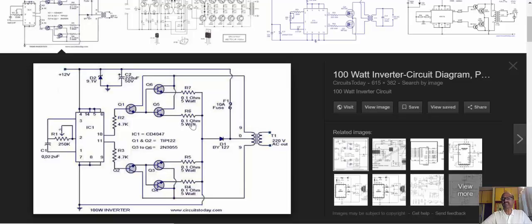So overall the circuit is not good, though it uses a digital IC. This is the variable resistance, and this is the capacitor to set the frequency, and once the frequency is set, this is going to be operating at that frequency. This is Q and Q bar. But a serious drawback, a serious mistake in the circuit, is that from 12 volt a 9.1 volt Zener diode is connected directly. It will fail immediately the moment you switch on, because there is no series resistance connected here.